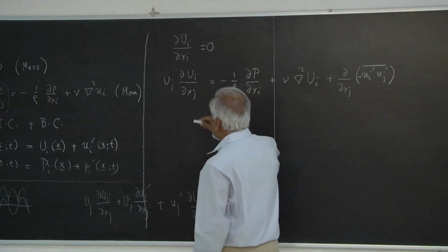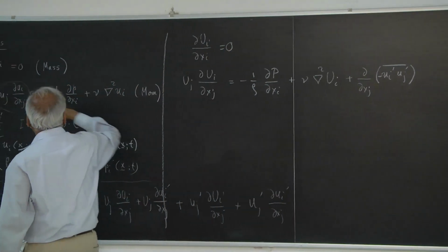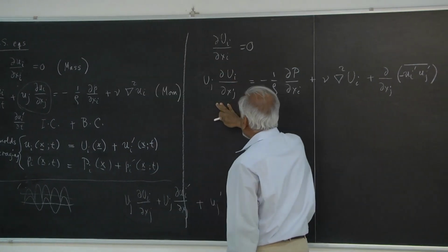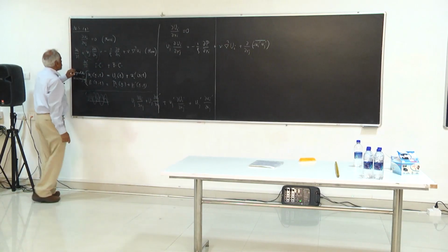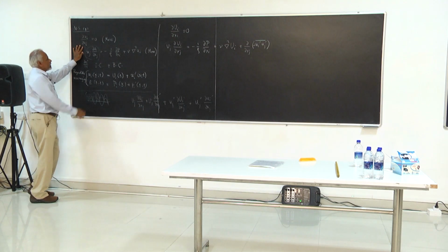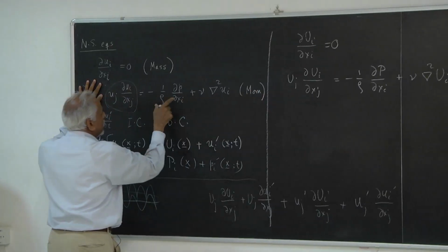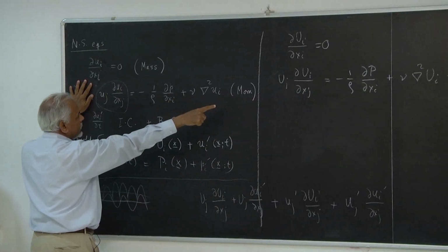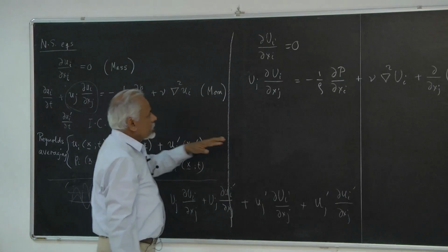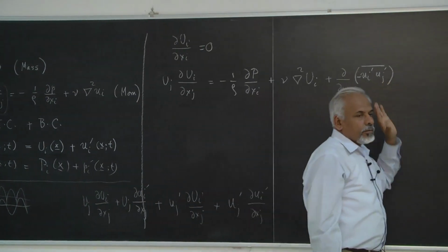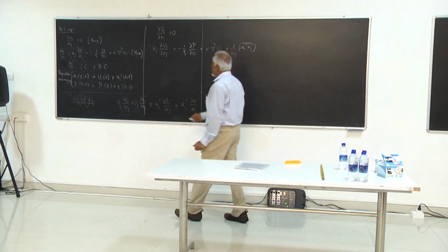Now, one thing you notice is that the mean velocity satisfies an equation that is different from the standard Navier-Stokes equations. Even forgetting about this term here, I have a thing corresponding to this one there, and a thing corresponding to that on the first term on the right-hand side, and a thing corresponding to that on the second term there. And then I have this additional term which includes fluctuations and has only fluctuations in it.